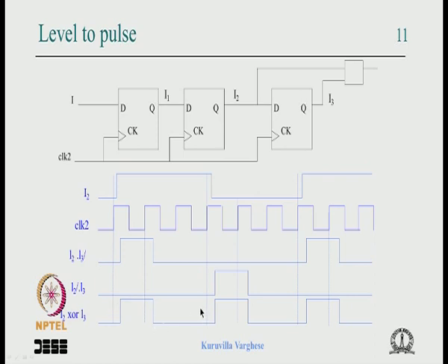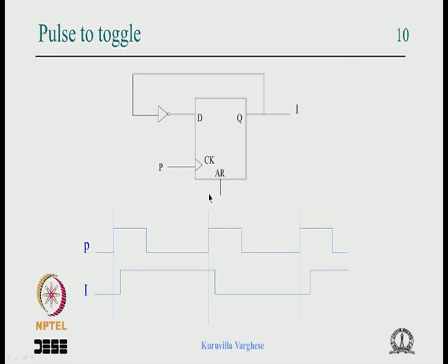So this is a very practical circuit, very much used, though there are some timing constraints which at this stage we will ignore. It is not that it works for all cases. There is some restriction because of this double stage synchronizer, because for the I2 to come here it takes 2 clock periods, and that means between these 2 pulses there should be at least a 2 clock period gap of the state machine, nothing to do with the pulse itself.